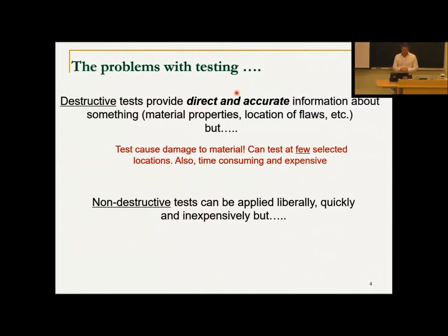But the problem is that this kind of excavation can damage the material. If we need to drill a hole or excavate, in some cases, this is not tolerable because we would damage the structure or the element beyond repair, right? So it can cause damage to the material, although it's needed. So we can do these, but sometimes we cannot do that in a very sensitive structure. And in some cases, we can do them in a few selected locations. So they're damaging, they also take time, and they're expensive, but they are critical because they are direct evidence.